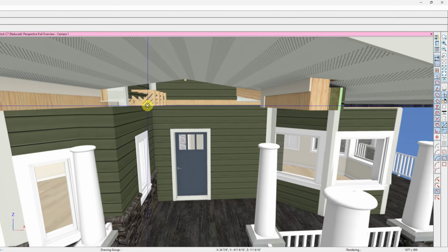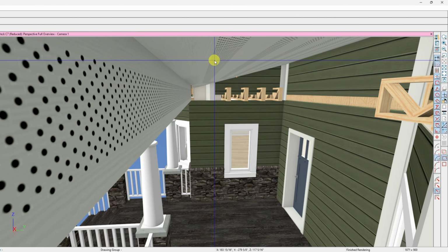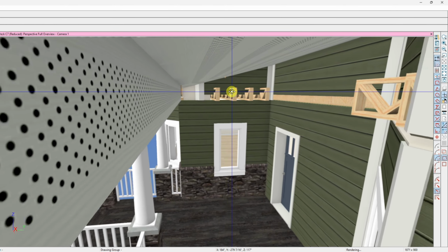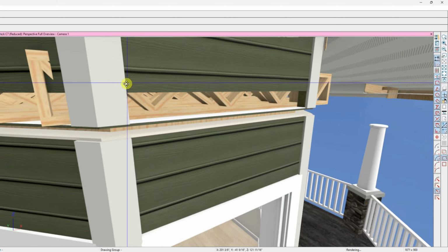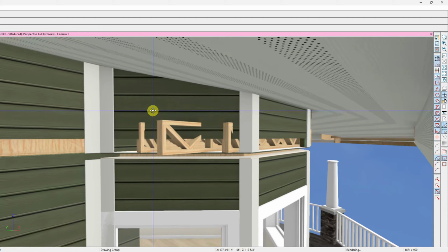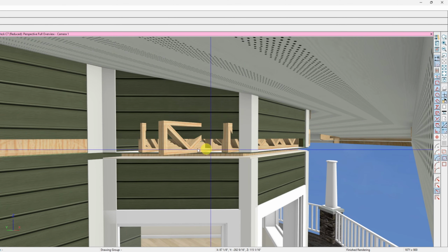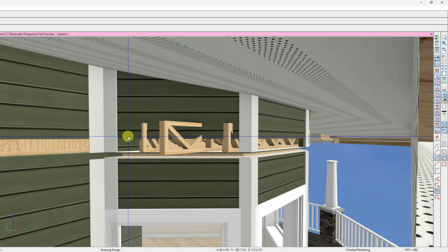Now, well, that's odd. Getting floor trusses coming through, and I didn't ask it to build the floor system. And these are going to rafters and not trusses as I'd like them to be. And part of that probably has to do with the fact that I've got a soffit up here. I've got apparently floor trusses popping through randomly in strange places. And I'm guessing that it probably has something to do with this gap or the way that the walls are not mending.